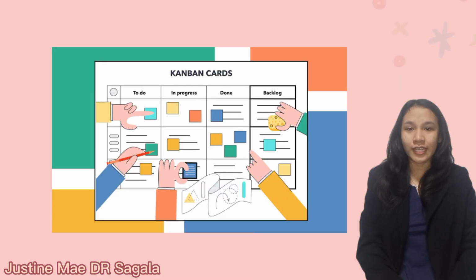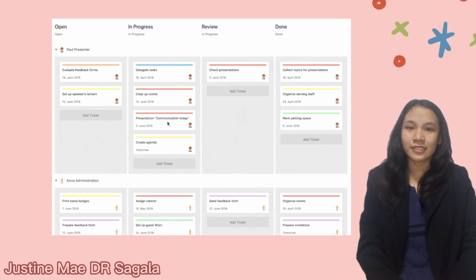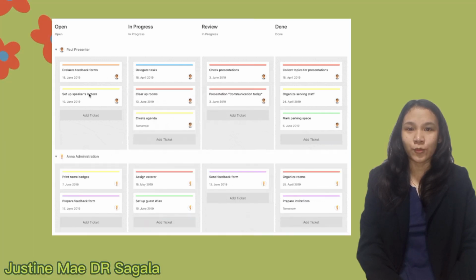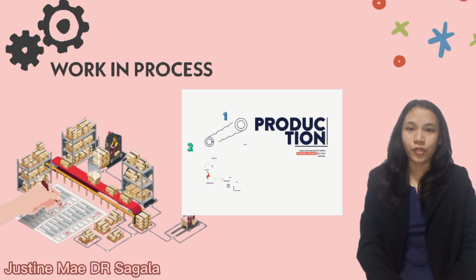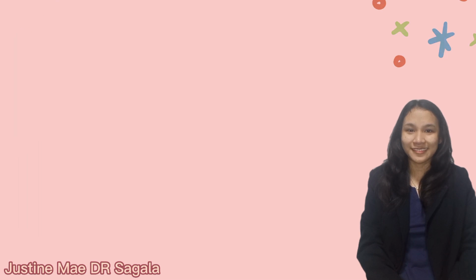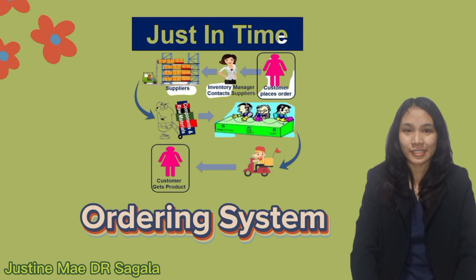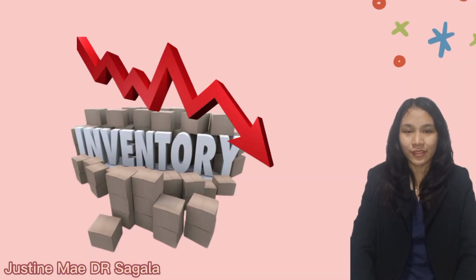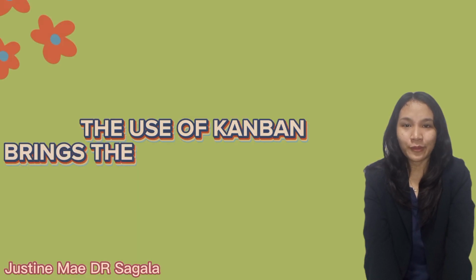The Kanban card contains all the information required for the job to be carried out on a product at a stage along its path to completion, and which parts are needed to be subsequently processed. The Kanban card is used to control work in process, production, and inventory flow. The Kanban system allows companies to use a just-in-time production and ordering system, which allows them to minimize their inventories while satisfying customers' demand. The use of Kanban brings the following benefits.